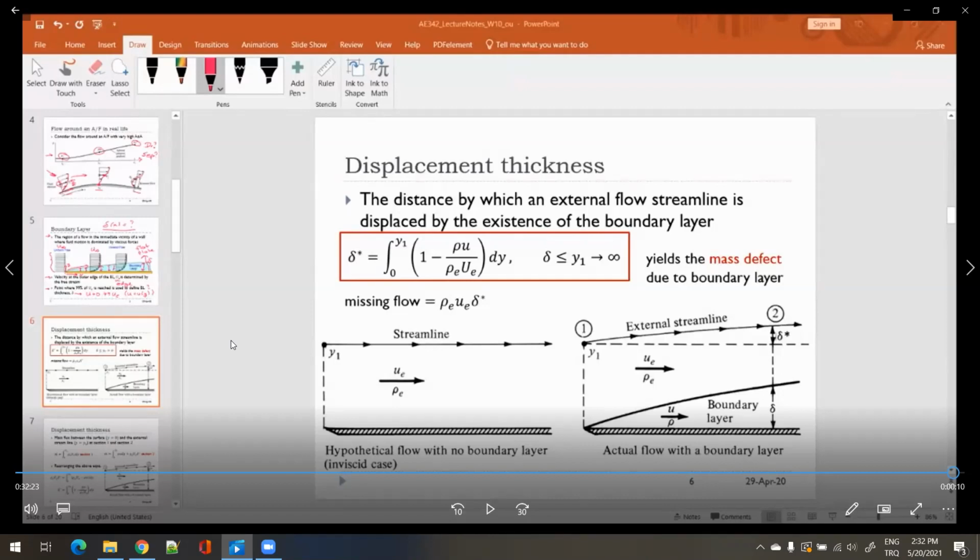If you cannot estimate by theory, we need to do experimentation in wind tunnels, okay? Because it's very difficult, or probably impossible, to do this during a flight test of a vehicle. So if we do not have good enough theory, we need to do at least wind tunnel tests to come up with these viscous flow related parameters, okay?